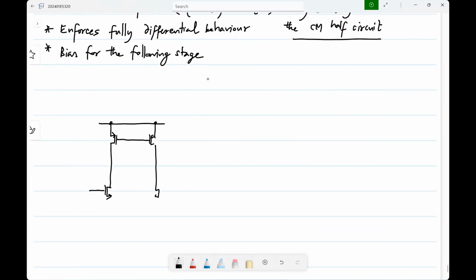So far, for a differential pair, all high gain stages basically look like two current sources fighting each other, right? On one side you apply a signal, or maybe to both sides in some cases. All high gain stages are like this in CMOS, in transistors. So on one side you can apply a signal, and the other side you can control the bias. So the same thing here. Using this side you can control the common mode. You can do it using this also, or you can inject an additional current there. All of those are possible. So you can see the number of circuits multiplies, but the basic principle is the same.